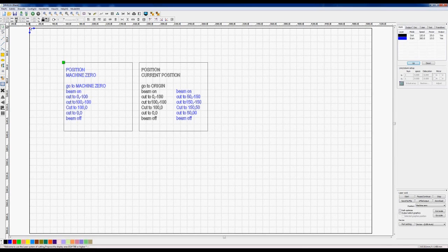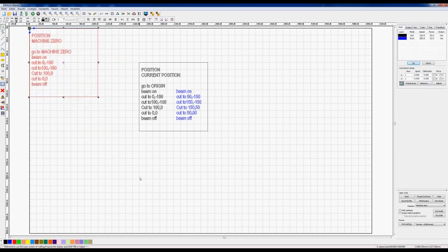And what does it do from there? It says, okay, I've got a program now which coincides with this point, because technically what it's done is lifted this point and driven it to 0, 0, which is exactly the same as us picking up this and moving it to that position. Or the machine doesn't have to make any adjustment or changes to the program to run it